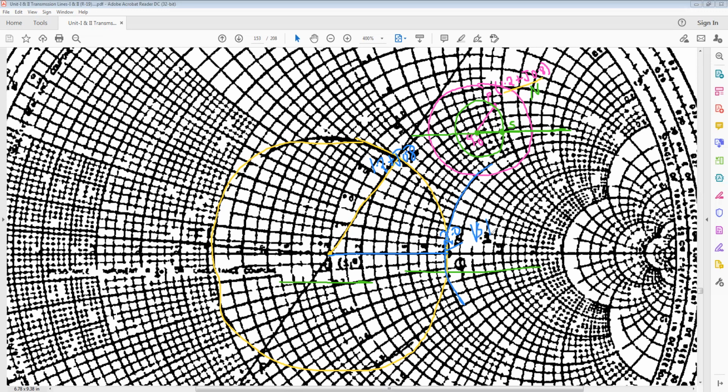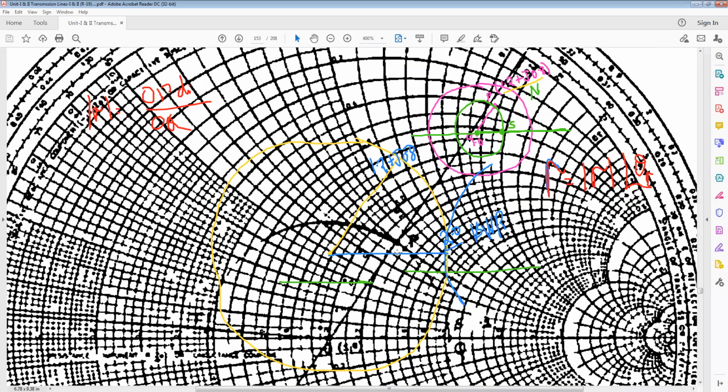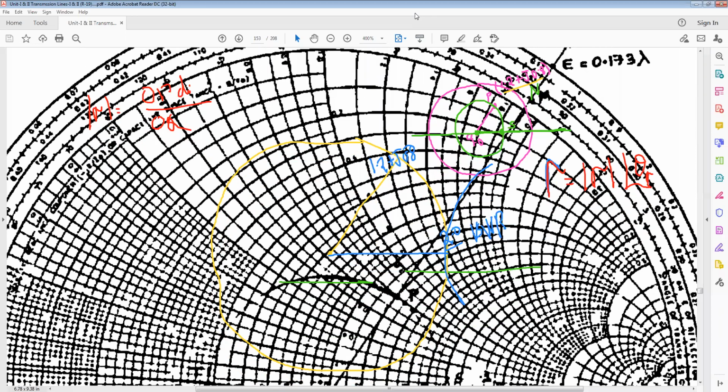Got it, my dear students? We got the VSWR, the voltage standing wave ratio. And also to find the reflection coefficient, gamma is equal to its magnitude and angle theta r. So now what is theta r? We got previously the value of 1.0, 1.2 and 0.8. The reflection coefficient magnitude is equal to the ratio of the distances OP and OQ. What is OQ? After plotting the point P, extend the line from the origin through P up to the point Q here. This is Q.